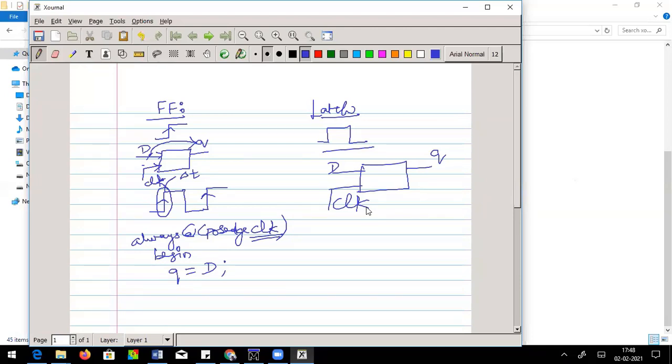No, that's not the right definition, because a clock is nothing but a signal, which toggles. And for this sake, it need not even be a symmetric clock. Any rising pulse from 0 to 1. As far as this signal is concerned, it could be a constant 1 or constant 0, no issue. Or even continuous 1, continuous 0, no matter.